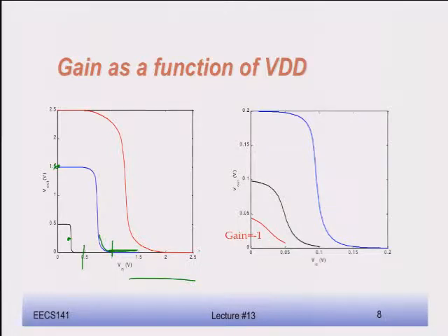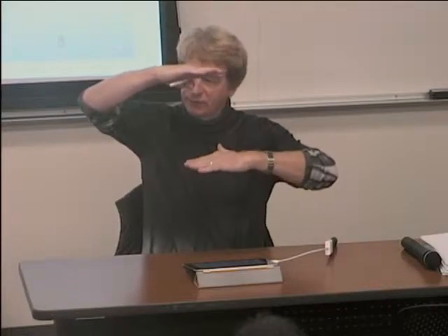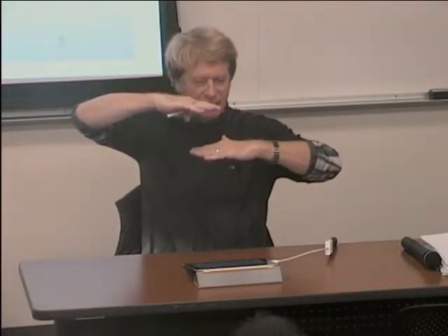Which shows something interesting: I can take the supply voltage of an inverter and start dropping it, and it stays an inverter. Even if the voltage gets very close to the thresholds. Like in this process, the thresholds are about 0.4? And I'm operating at a supply voltage of 0.5. Which means that my transistors are barely on. It's quite amazing, isn't it?